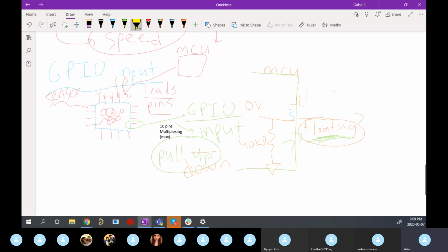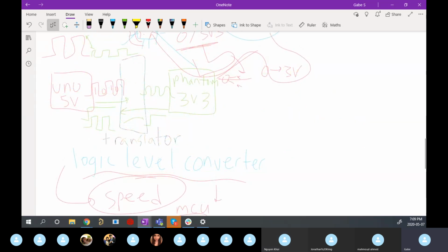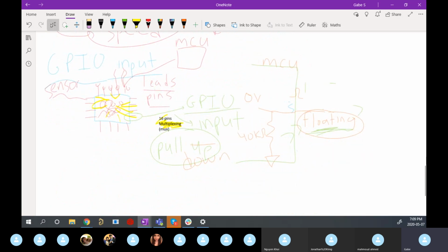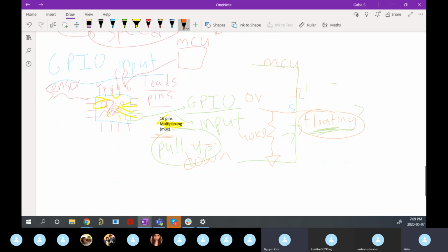Usually you set up your multiplexing once, right? So you set this up to happen once at the very start so you can configure exactly what all your pins are going to do. And then you're not changing that usually mid-operation. So you do that once, and then the logic level converter happens outside of your microcontroller, right? So these two are the microcontrollers. This is some third-party external chip that's doing my translation. And so this can do whatever it wants whenever, but that multiplexing happens usually just once in this scenario, where you're setting up a pin for the first time. Does it make sense? Yeah.